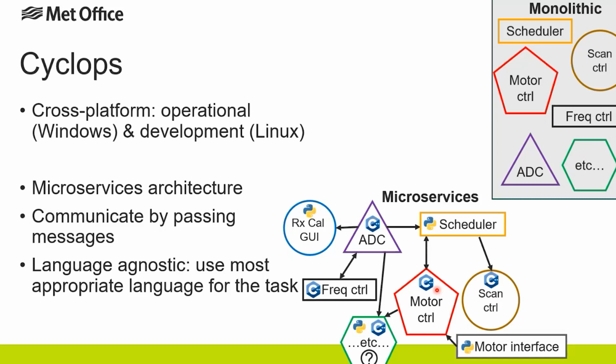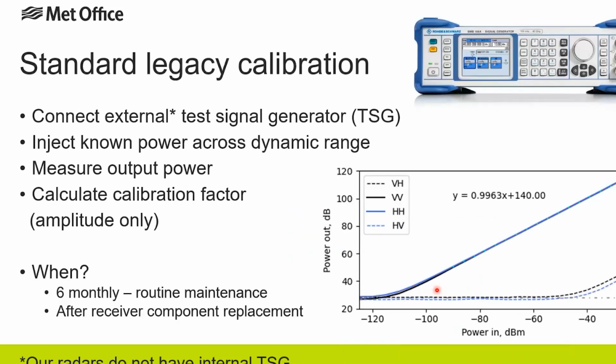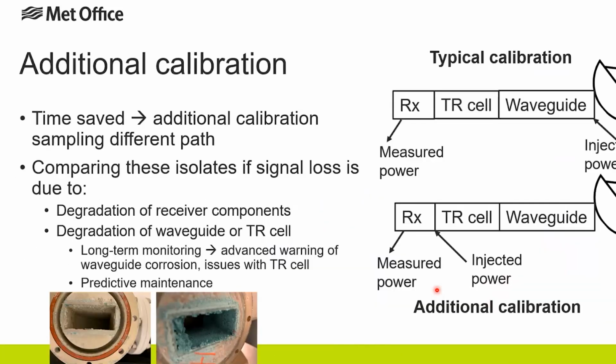Is it waveguide corrosion? Is it failure or location based? So this particular example was a failure in the dehydrator. It caused quite a significant amount of corrosion. And I think it was a joint that had a higher probability of galvanic corrosion as well, so that really accelerated that.